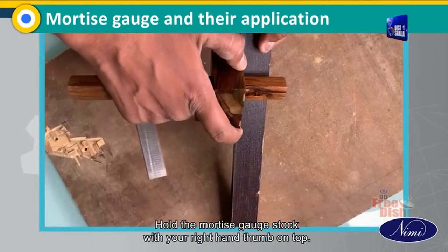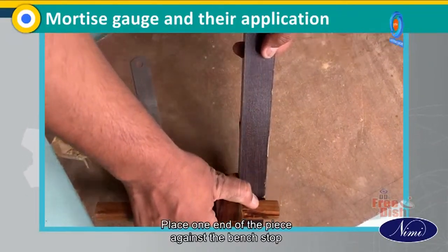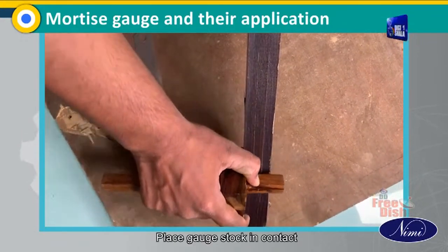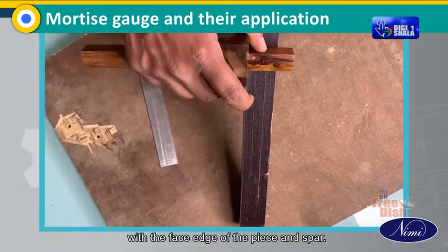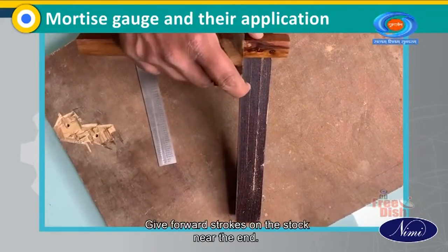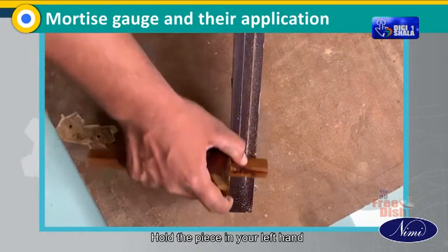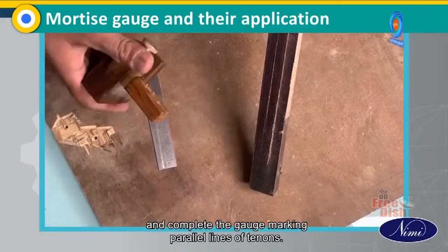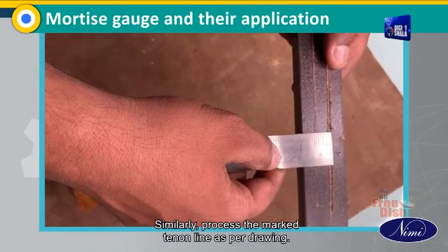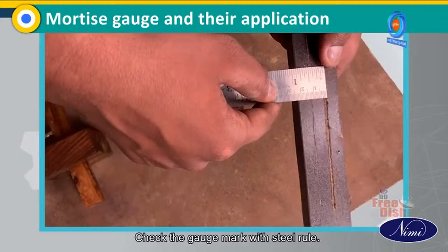Hold the mortise gauge stock with your right hand thumb on top. Place one end of the piece against the bench top and the other end in the left palm. Place gauge stock in contact with the face edge of the piece and spur touching the piece lightly in slanting position. Give forward strokes on the stock near the end. Hold the piece in your left hand and complete the gauge marking parallel lines of tenons. Similarly, process the marked tenon line as per drawing. Check the gauge mark with steel rule.